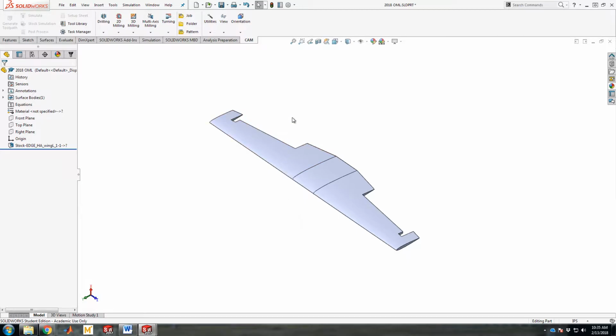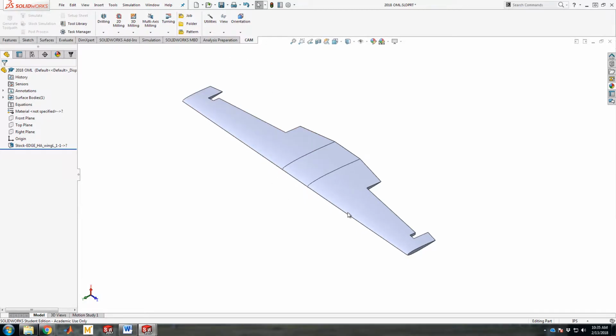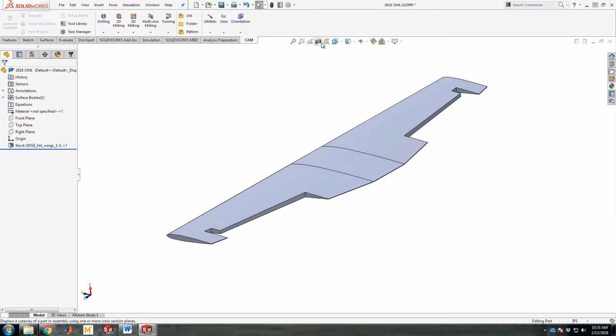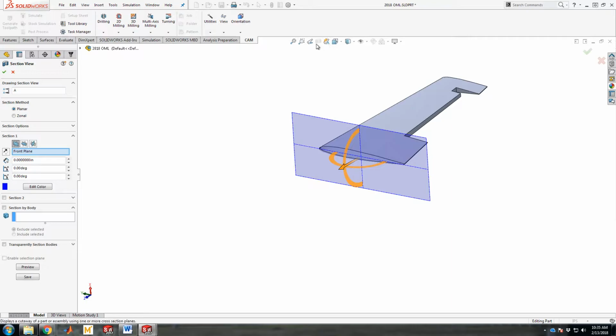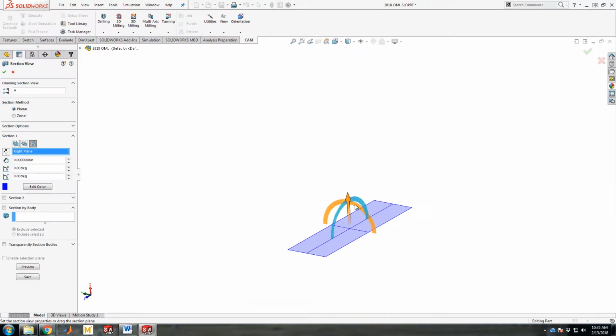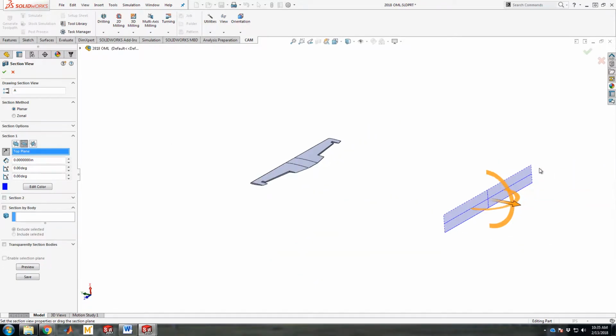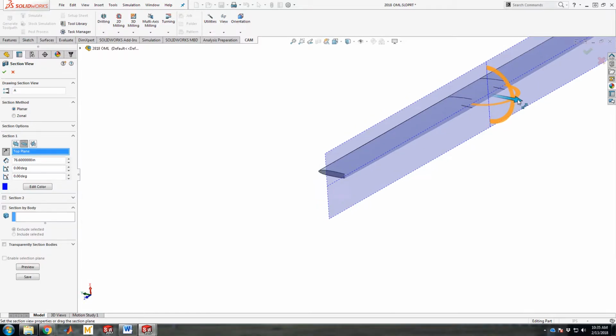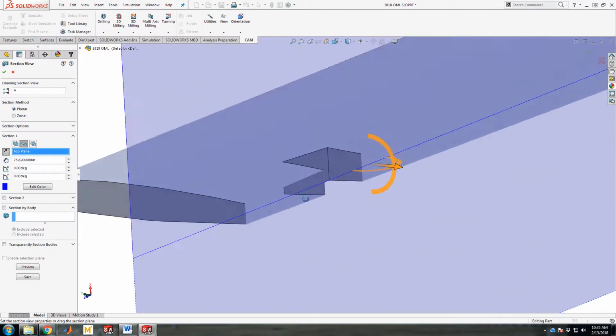So, disclaimer over. The first thing to understand is that this wing OML that's been given to you, the download that you're seeing, is a surfaced part. If you go to split, which is the icon I just clicked on, you should change the plane through which it's actually cut. Let's use this plane, actually slide it up. You can see if I zoom in all the way inside the wing, there's no material. It's not a solid body.